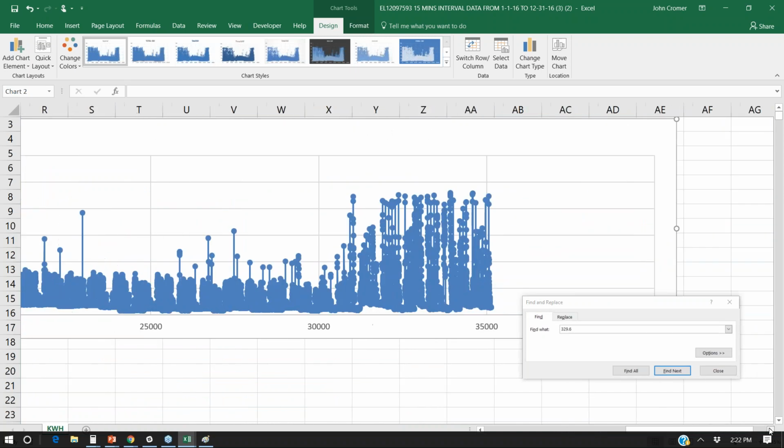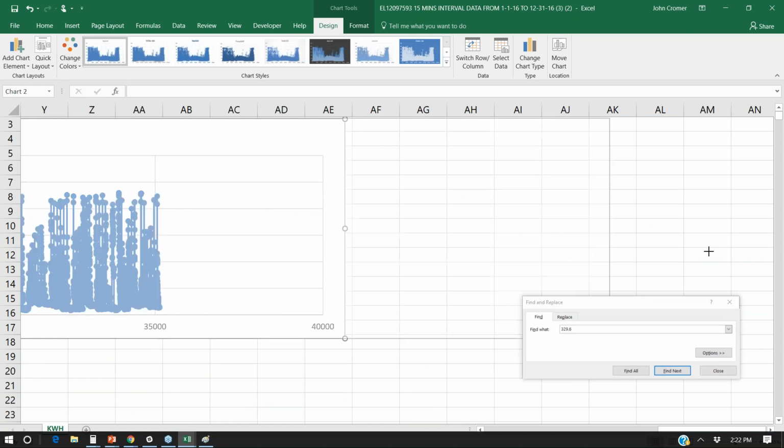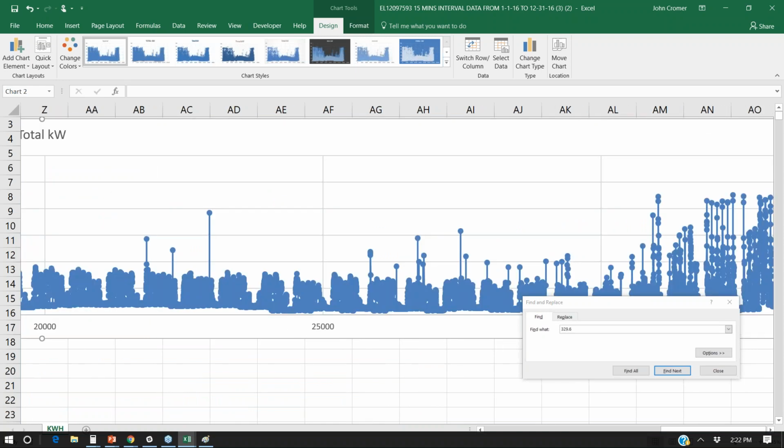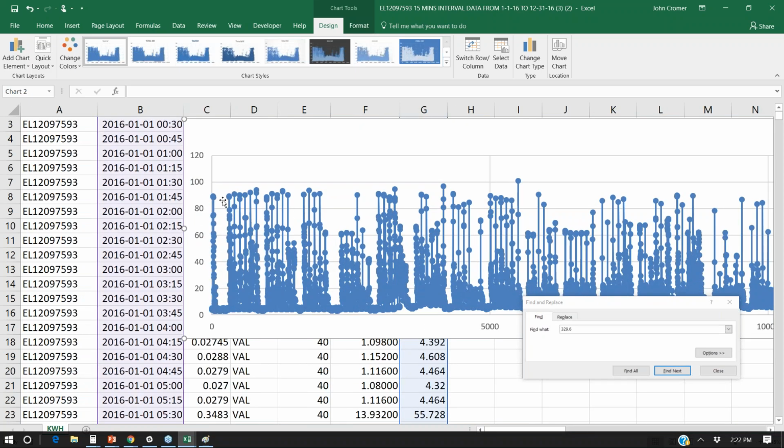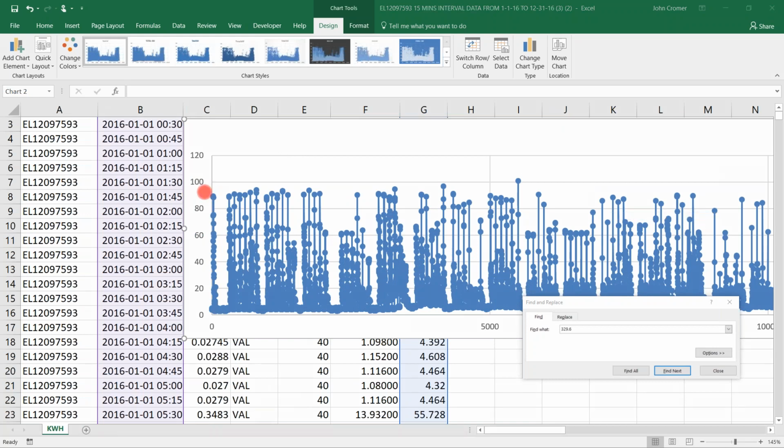Basically, what we'll see as this chart gets wider and wider is what we're about to see in Energy Toolbase. We see very large, spiky curves of power draw for this client, as heaters are clicking on and his building is surging all the way up to 100 kilowatts in heating demand, but his base is way down here at 14 or 15 kilowatts. And this is optimum.